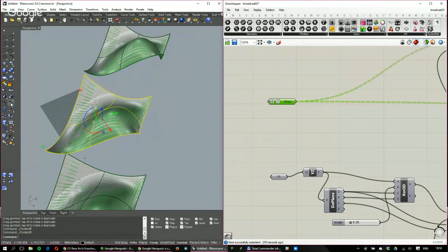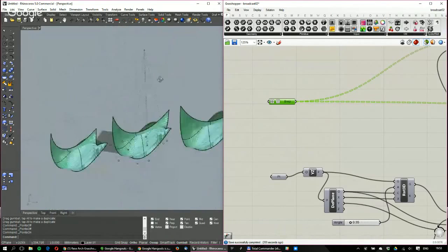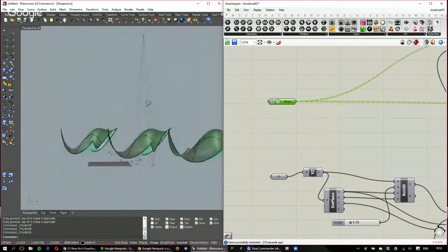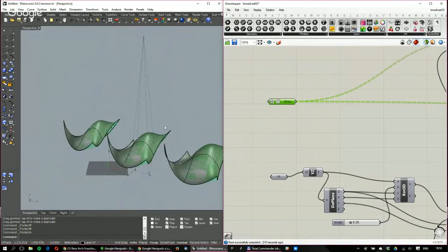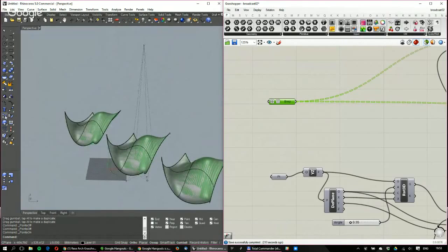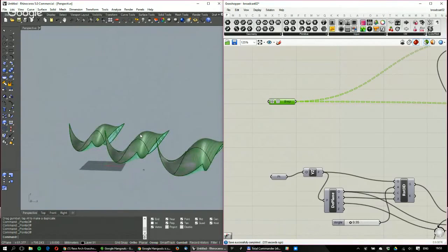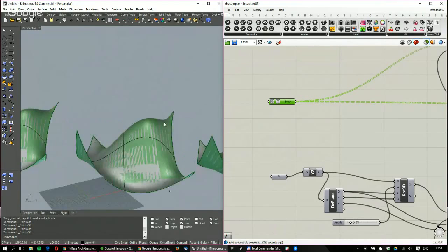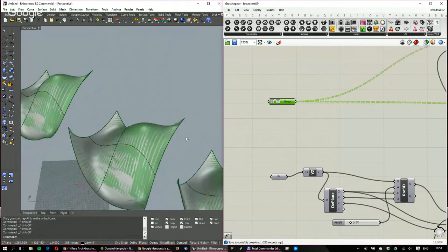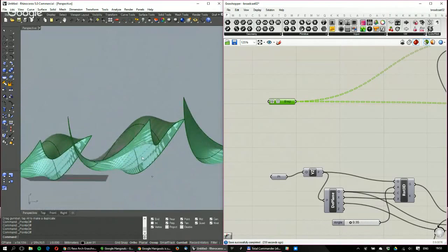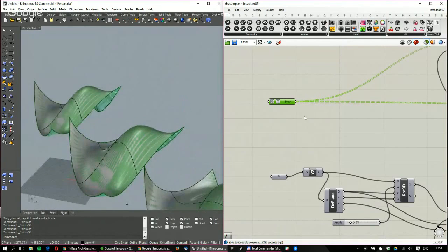If you look at the control points here, you see that there is something that looks like a very edgy mesh structure, and it's smoothened out. And that's actually true. That's how the NURBS geometry is actually made. This is called a polygonal hull, and that's an unsmoothened mesh. Then you smoothen it, and you end up having this nicely smoothened out shape. So let's create a mesh using the logic of the NURBS smoothing.